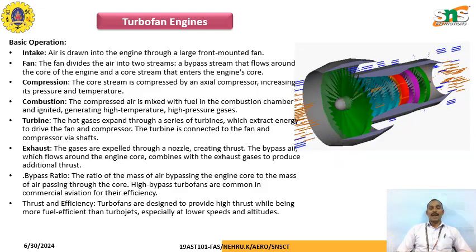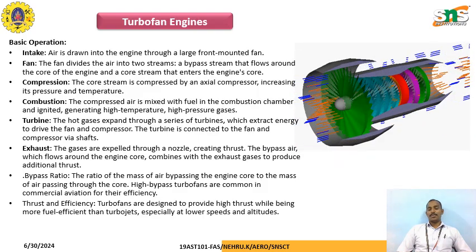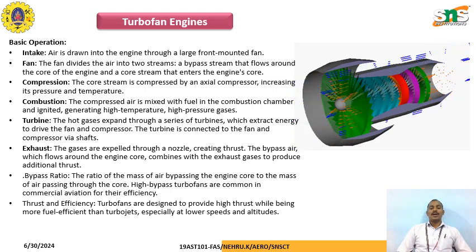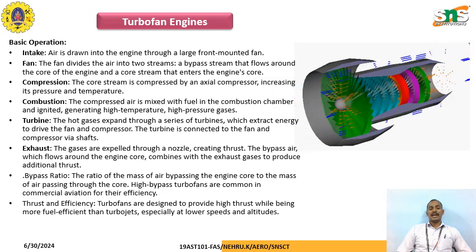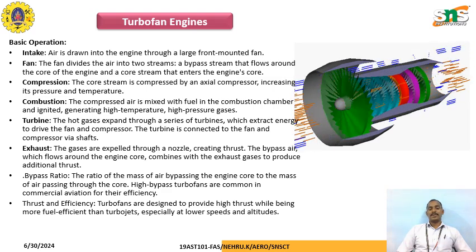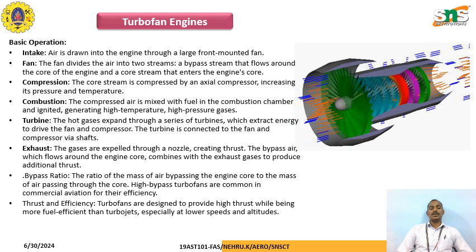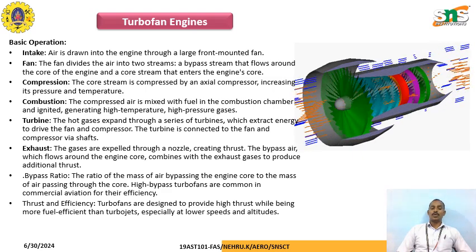Next one, turbofan engine. The basic operation is intake. Air is drawn into the engine by the large front-mounted fan. The fan divides the air into two streams: a bypass stream that flows around the core of the engine, and a core stream that enters the core engine.